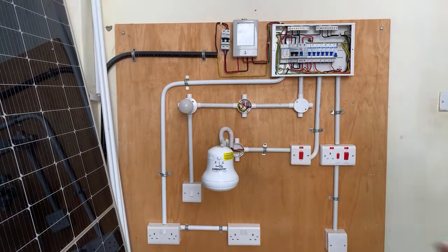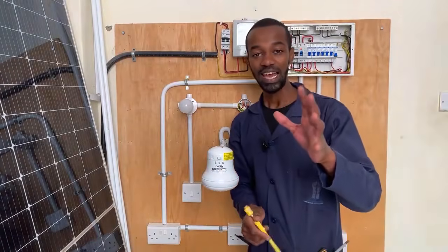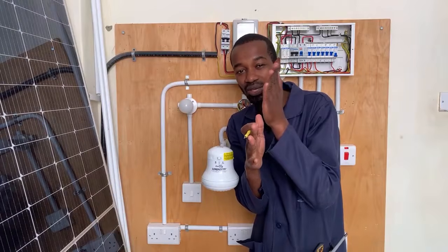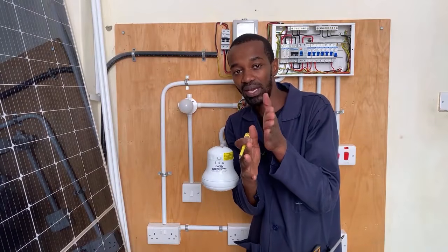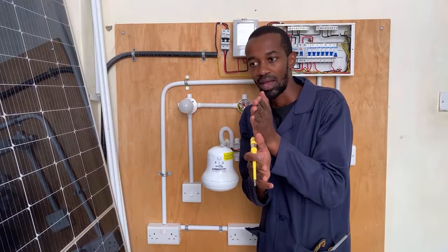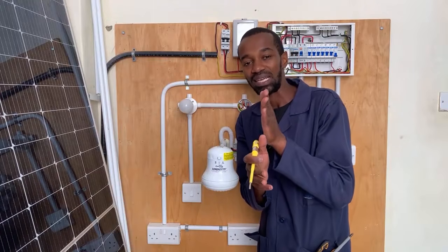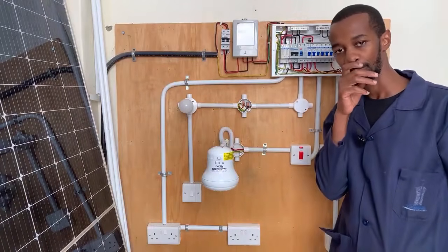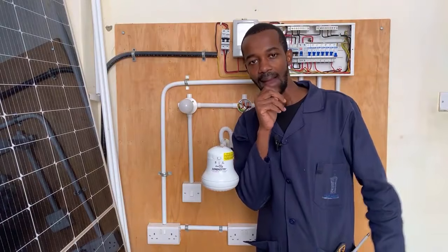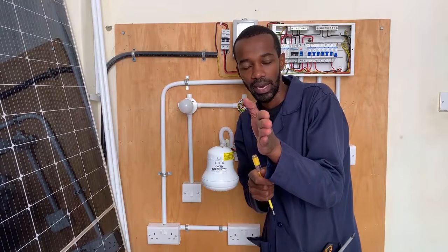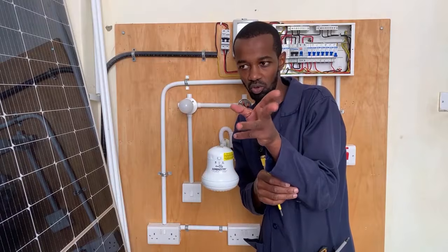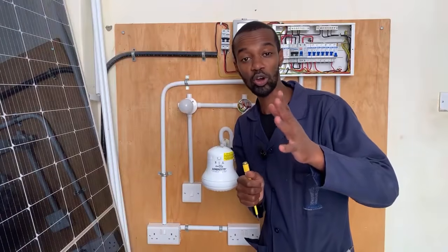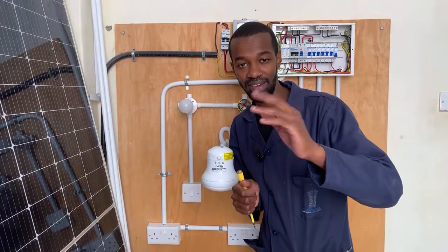Again, remember, in a house, especially these big houses, you'll find that there are several circuits. There is a circuit that is supplying the security lights and the common area sections. A smart electrician will ensure that one is a single circuit served with one MCB. And then you have the sitting room and probably two of the many bedrooms, and then the corridor and the dining.